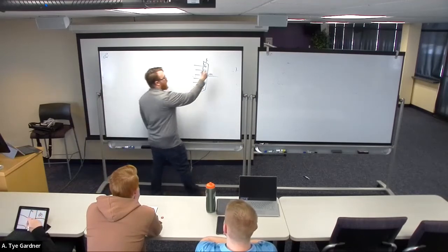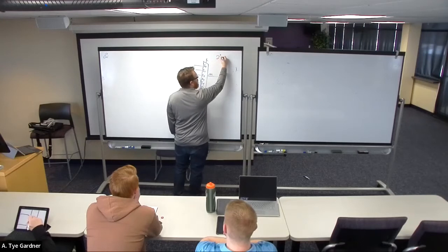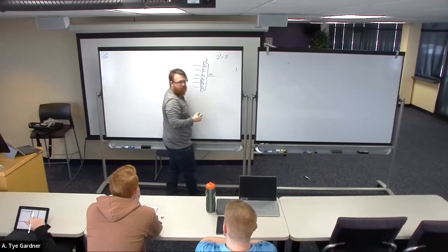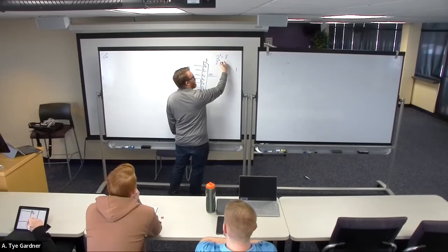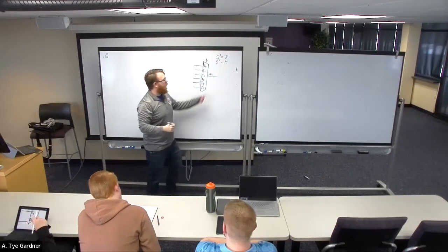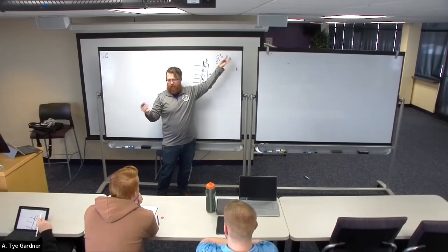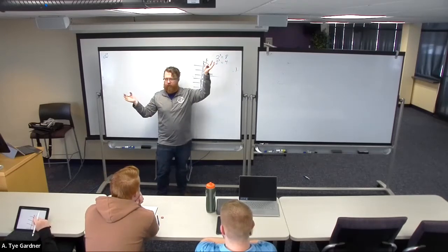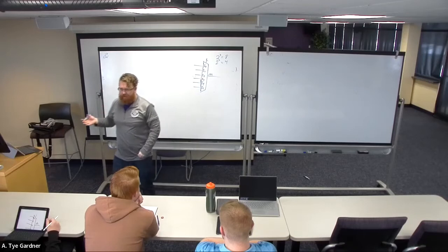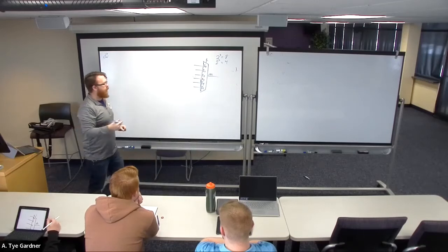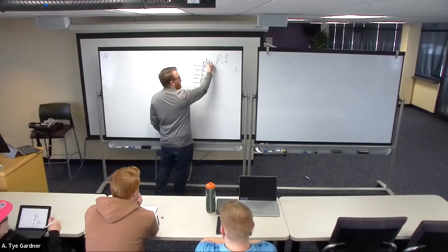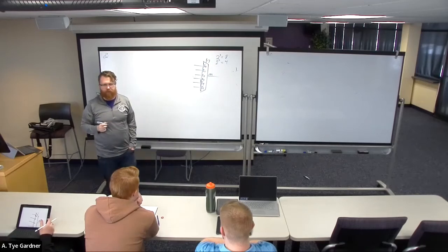Because 2 to the 3 is 8. 2 to the 2 is 4. 6 options doesn't fit in 4. I need to go to the next size up. That means it's going to have 2 options that aren't used, which is okay, but I need at least 3 bits. So that makes my select signal 3 bits.